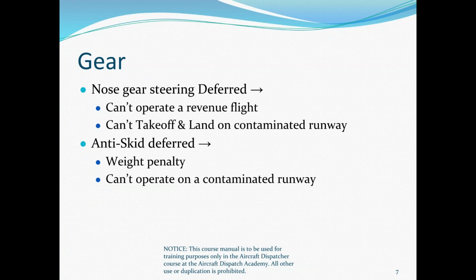If the anti-skid is deferred, what do you think the anti-skid system is? I mean, we kind of talked about it, but it keeps the aircraft from skidding on landing. Yeah. So think of it like the ABS system in your car, automatic braking system. It basically just prevents the wheels from locking up when you land and apply the brakes.